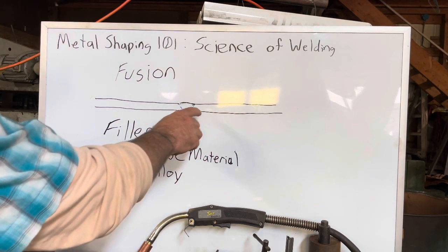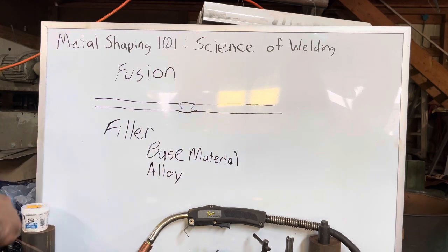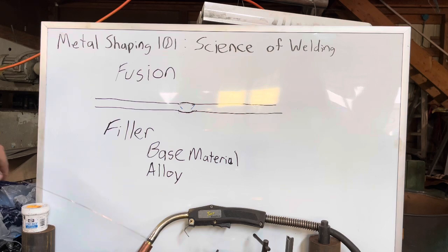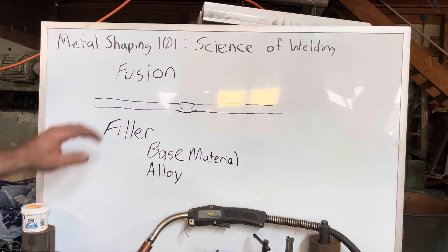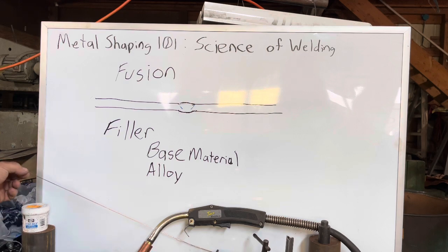We're going to be able to come in here now and polish that out and make the weld even more invisible than we could if we had fused it, where we might have a slight low spot there. But it's just one of those things you have to consider. What filler metal are you using? What filler metal do you need? What are your parent metals? And understand that filler metals do have a job. They have oxidizers and things in them that are meant to keep a better puddle and a better fusion.